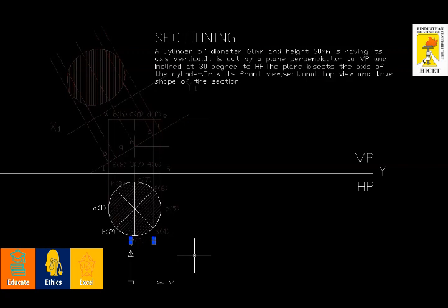See, under A, there will be 1, point number 1. Under B, there will be 2; the top side is ABC, and the bottom side is 1 to 3. So when I look at point A, under point A there will be 1 at the bottom side, which means A is visible and 1 will be hidden. So I'm naming it this way, A in bracket 1, B in bracket 2. Similarly, I'm going to name all the points.